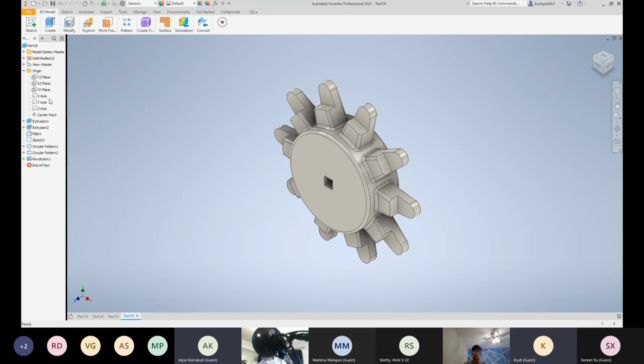Yeah, for sure. So what I basically did there is I wanted to create a rectangle. You have to think backwards, right? I want this part, the protrusions, to get cut out. So in order to do that, I probably need some sort of rectangle that revolves all the way around. The key step here is to pick the correct plane to create that rectangle to revolve around. The correct plane here is the XZ plane.